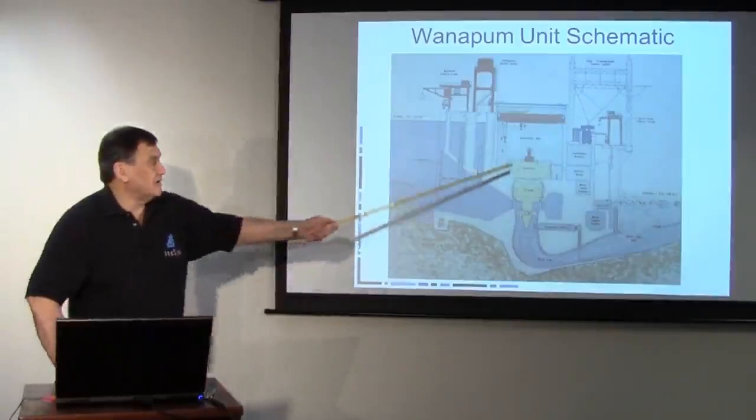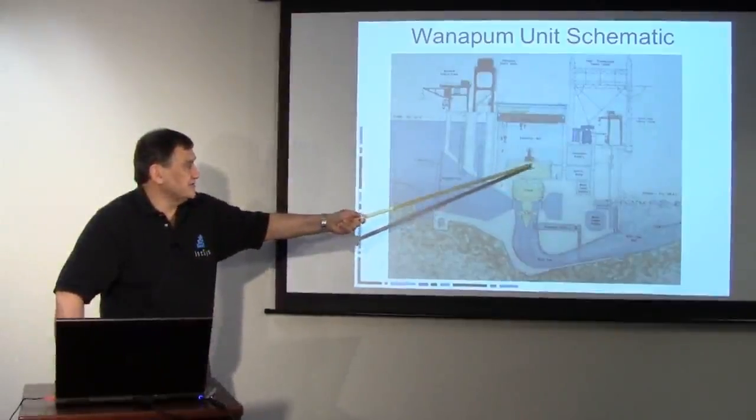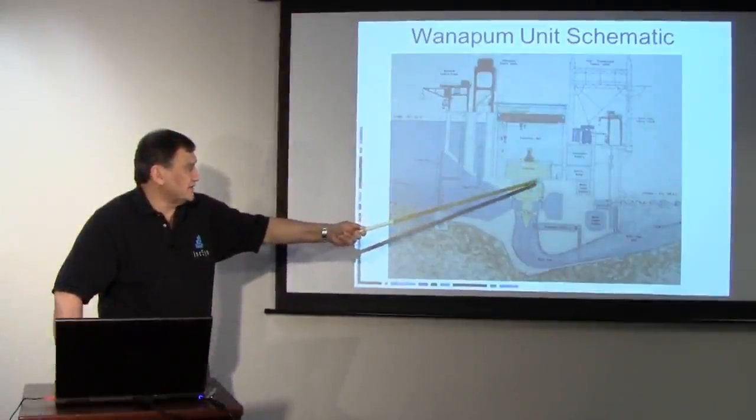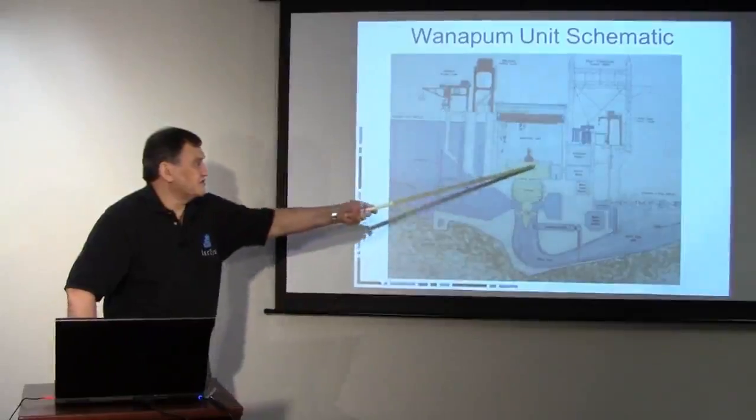From a system operator point of view, one of the things you have to be aware of is what's needed to operate this unit as a black start unit. Basically everything internally can be started except for the thrust bearing. There is a bearing at this location right here. Under black start conditions, the turbine is at standstill, and so the issue is how to get that turbine rotating. The main thing you have to do is provide high pressure oil to the thrust bearing.